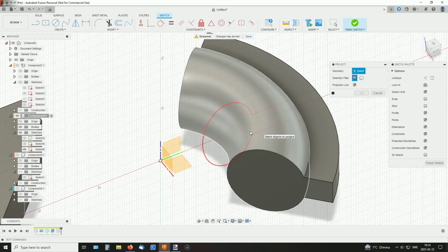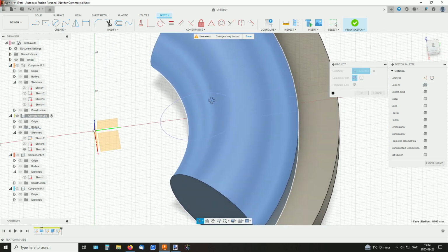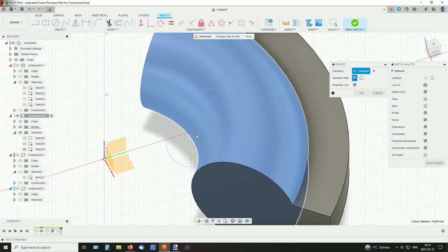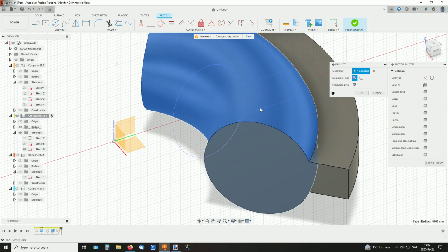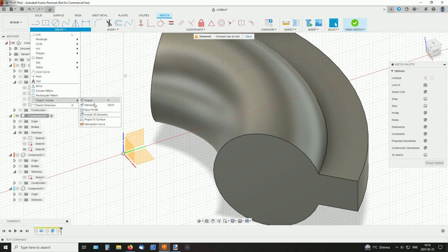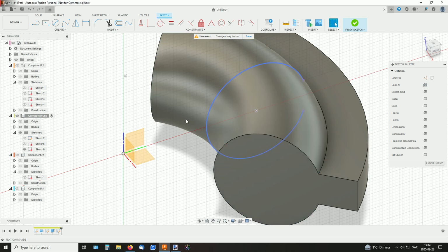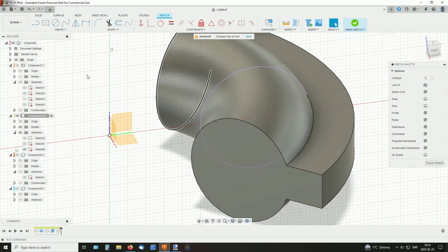And if I try this surface, as you see, it projects something, but it's outside. I wanted the line to go exactly where the surface was, where it intersects. That means I have to use the other one. Intersect. Oh, this one. Okay. And there I got my line. So now I can continue my sketch, and lines I create can snap onto that geometry.